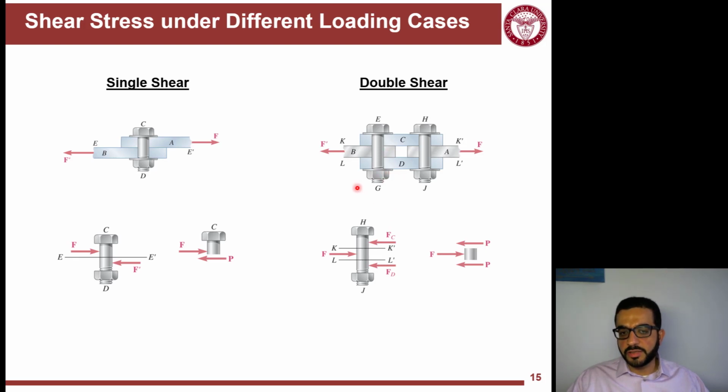Why do we do that? Because probably the nail's shear capacity cannot carry this whole F, so we splice the connection to be able to split the force over two shearing actions, not one. Also, this connection here is more symmetrical with the double shear than this one. There's some little eccentricity here that might cause problems. So this is more concentric loading than this one.